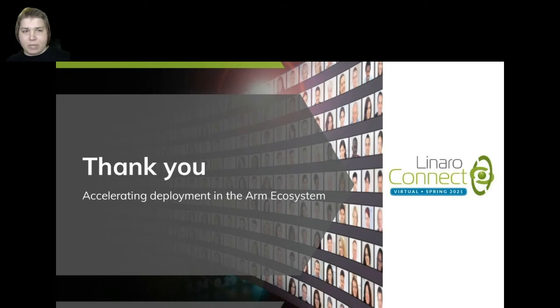Those manufacturers created their own header, which was so high that I was not able to add mezzanines on top of the board. With the new Spec V2, it's necessary to have your debug UART over a USB to UART adapter on board, so you plug in your USB cable. And that will hopefully end the pain of cutting down your UART header just because you want to add your mezzanine on top.